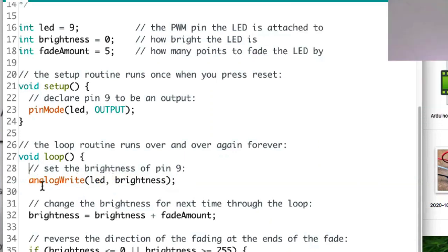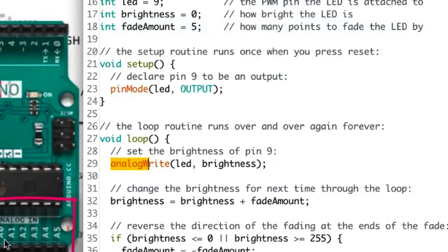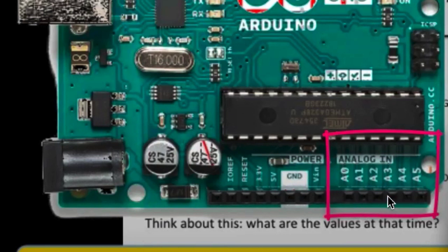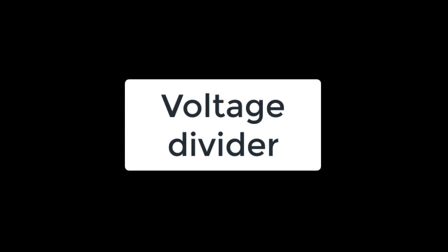This is how Arduino, or most computers today, handle the analog. Now, however, you do have an analog pin generating a real analog signal. I mean, we're using the digital pin to simulate an analog signal by PWM, but we can also have the real analog pin generate a voltage in between 0 to 5 volt. And this one can also read in from 0 to 5 volt too, right?